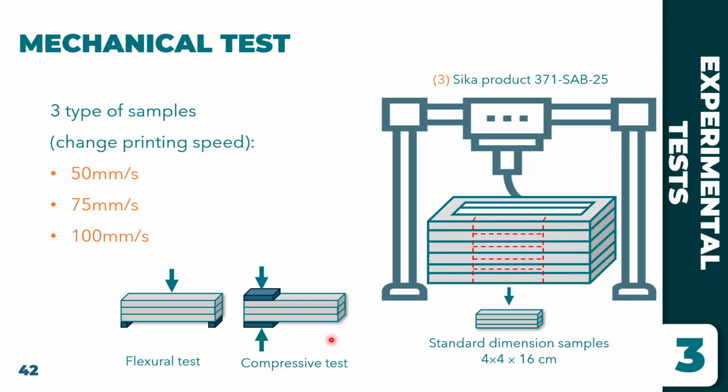And in terms of mechanical tests, I want to study the impact of 3D printing on the mechanical strength of the sample. Here is how I print the sample, and here is how I cut the sample into the standard dimension, and here is how I do the flexural test and compressive test.